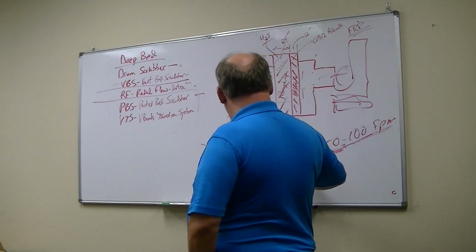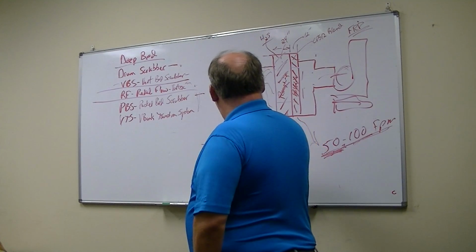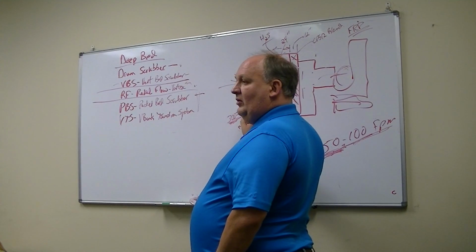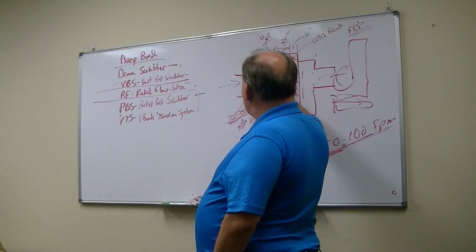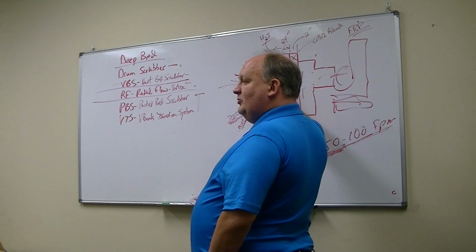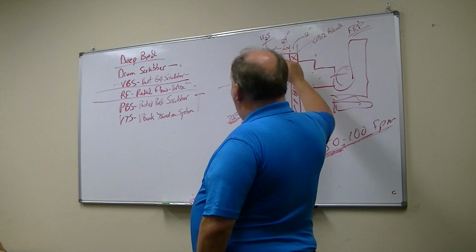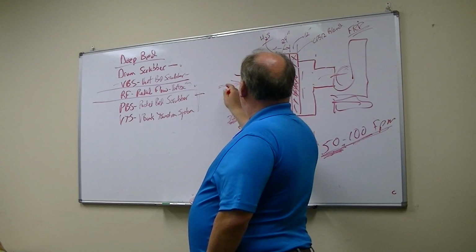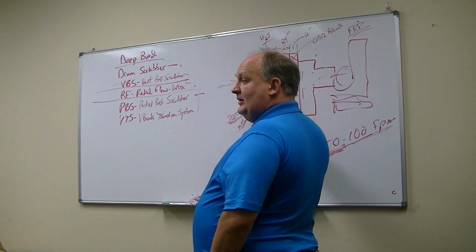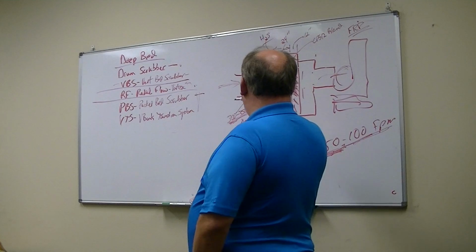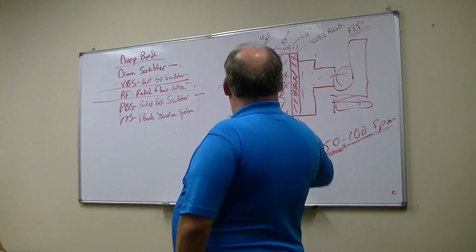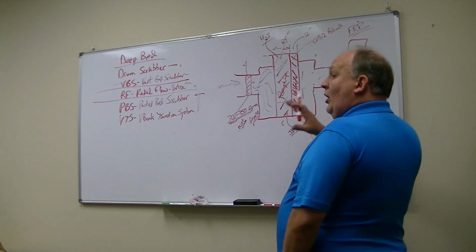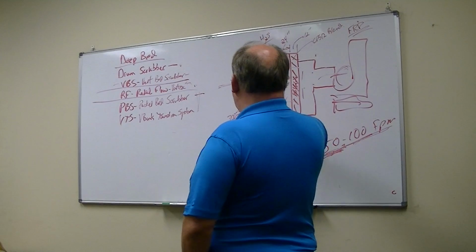So anyway, that's kind of a little sidestep on mist and grease filters. But because we're running the air through there at 300 to 350 feet per minute, we need a much smaller filter. The area of this filter needs to be much smaller than the area of the media bed, okay? And that way, we have the same airflow going through here, but at different velocities, all right? So that's what happens there. Now, we'll get through this, and then I'll also talk about the design for not odor control, but for industrial electronics, because it's going to be a little different.